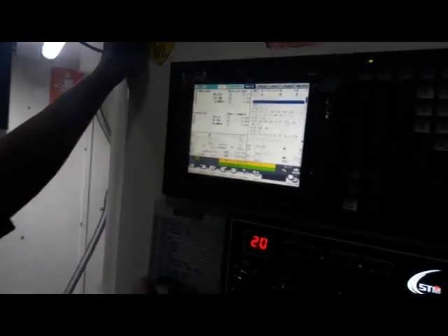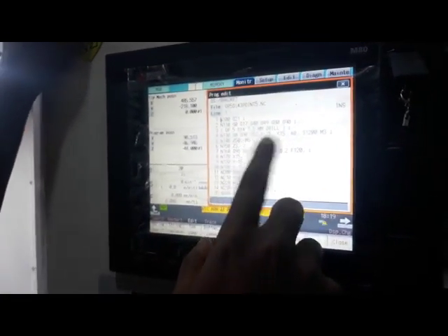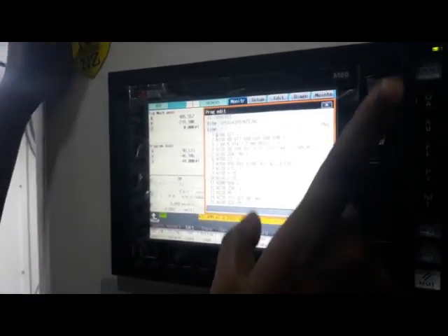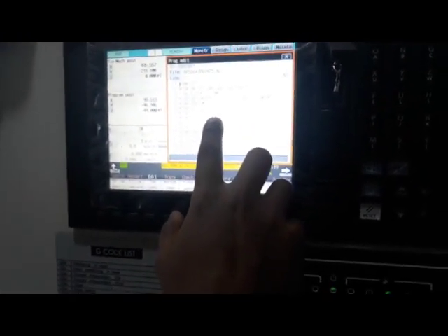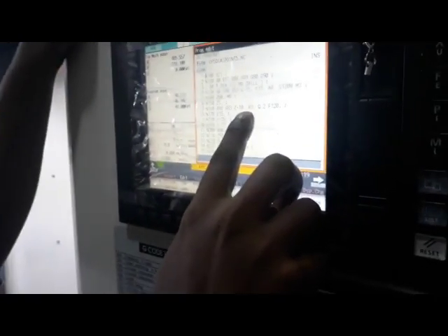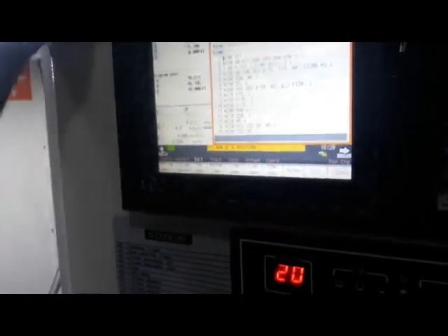number. Now I'm going to take z-axis all the way up, search for the program that I already made. This is the program, the 3.5mm drill. Okay, so I've opened the program in here to just double check if all the parameters and codes are correct and the position is correct. So I can see G57 and all the header command is good. G98, G83, which is for peck drilling. So it's going to go 10mm deep and a retract of 3mm with a depth of cut of 0.2. The feed is 120, so it all looks good. So we can go ahead and machine this.